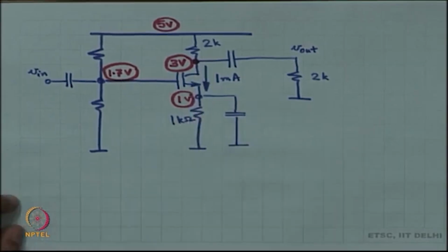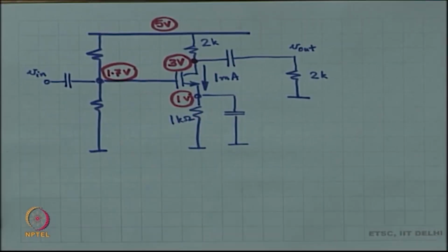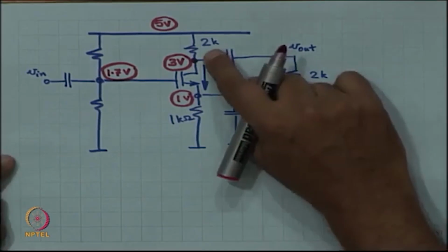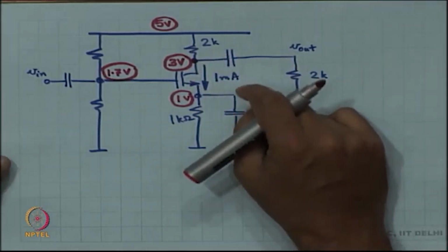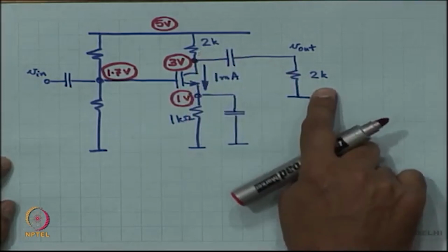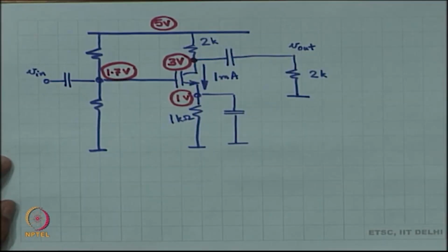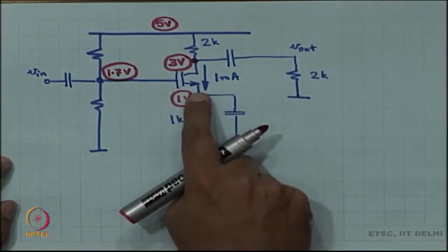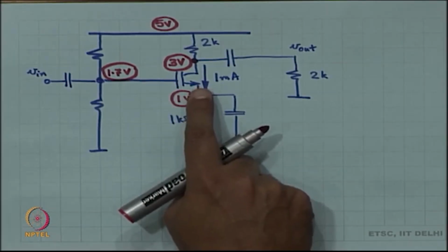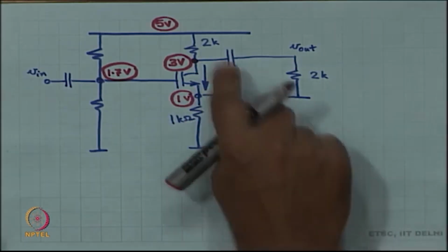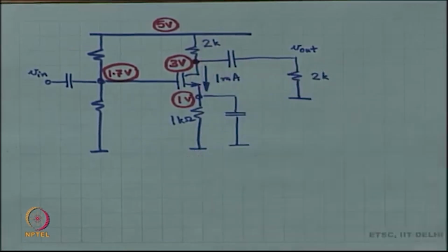Fine. Okay. So, condition number 1, VDS has to be more than VGS minus VT. By the way, what is the gain of the amplifier? Look, it is the same as before, it is still minus 10 because I have got 2K in parallel with another 2K at the output. Okay. GM is still equal to 10 millisiemens, right, and the output impedance is 2K in parallel with 2K.